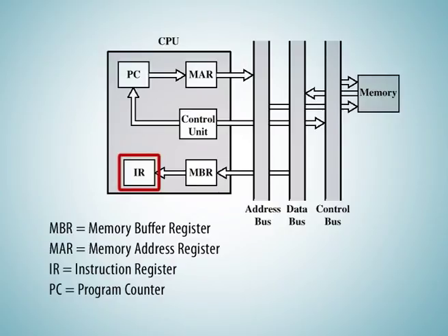At the beginning of the fetch cycle, an address of the next instruction to be executed is placed in the program counter. The first micro operation is moving that program counter value to memory address register, because this is the only register connected to the address lines of the system bus or address bus in short. The second micro operation is to bring the instruction from the main memory to CPU. This involves placing MAR on the address bus and activating read signal of the control bus.